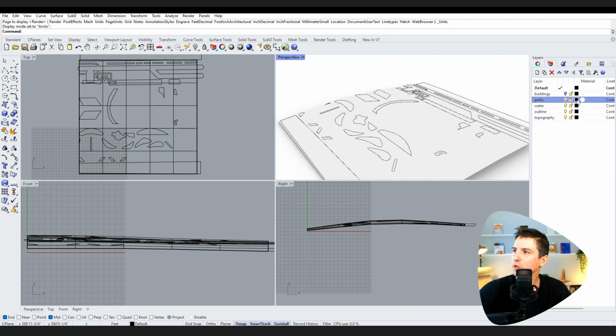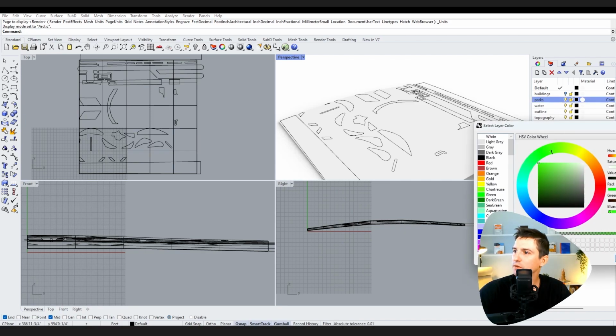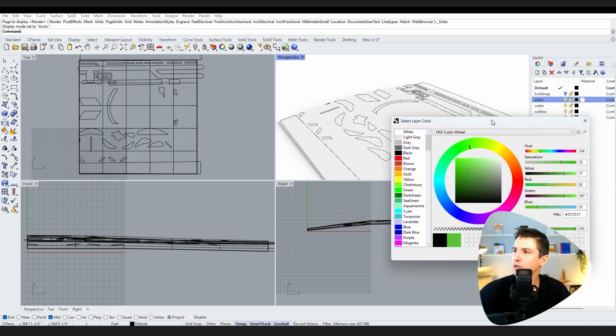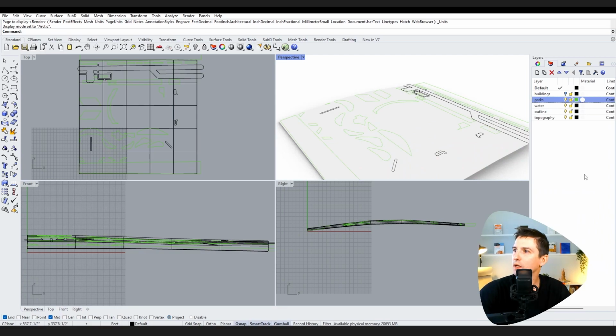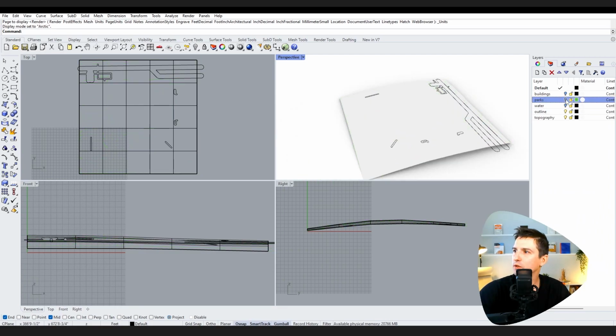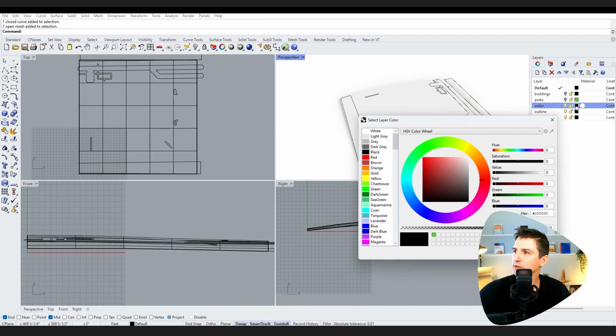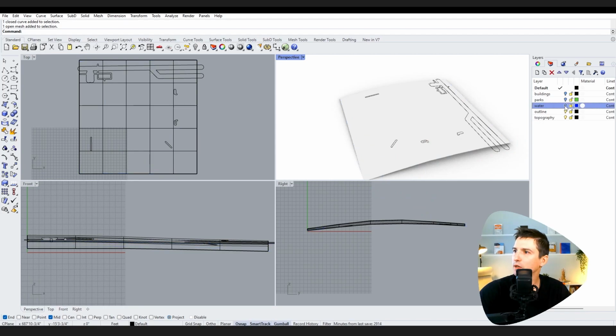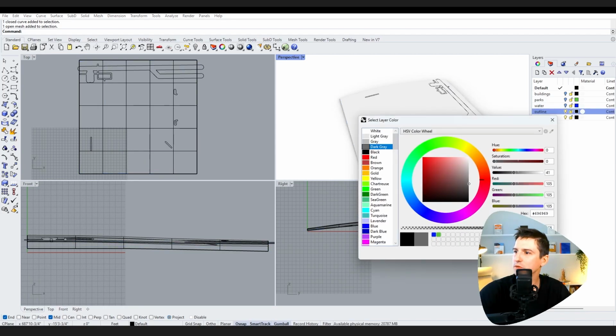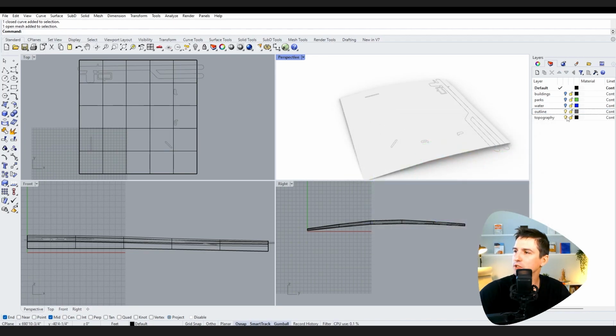What might be handy to help organize the layer is to give the layer something that makes sense in terms of color. If you would like, say okay. And then all those parks are showing up green. We turn off parks. Water are these two rectangular forms here. So water, let's go and change that to blue. We'll turn that off. And then outline, that's the roads and paths. Change it to like a dark gray just to differentiate.